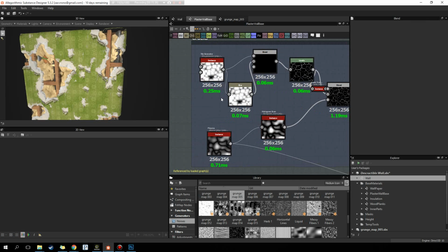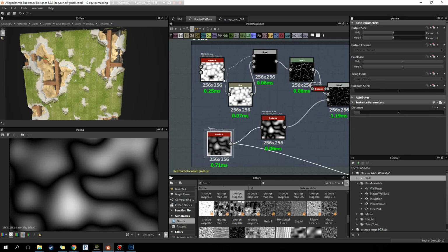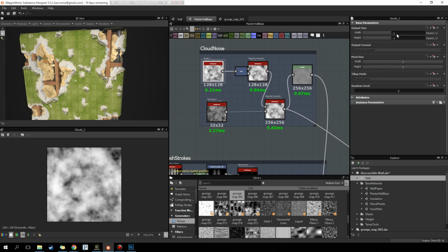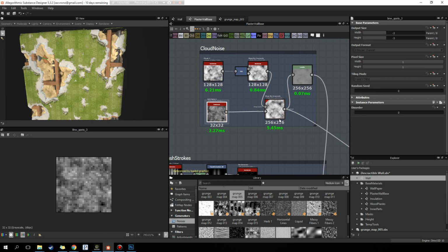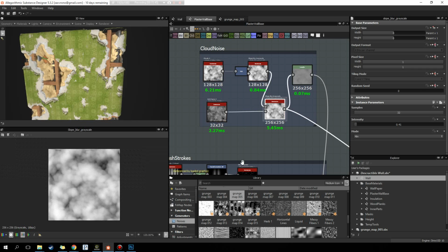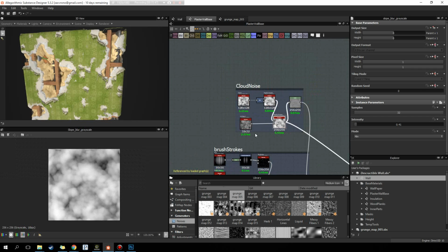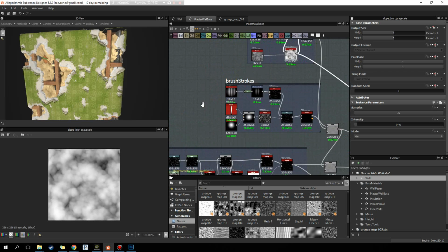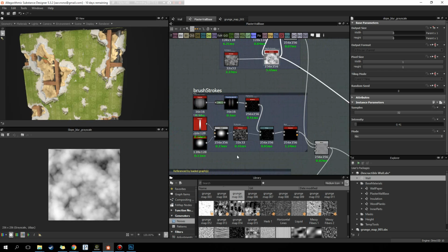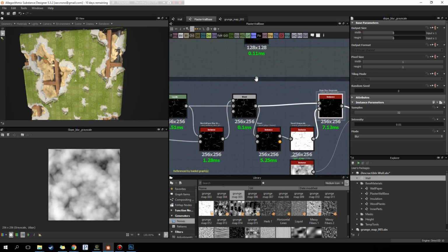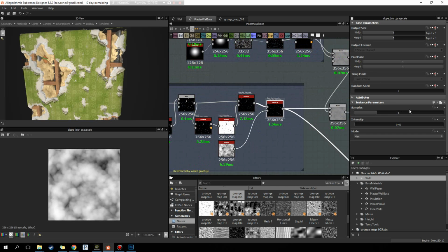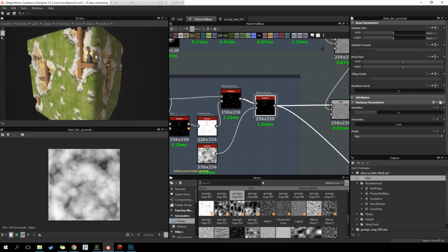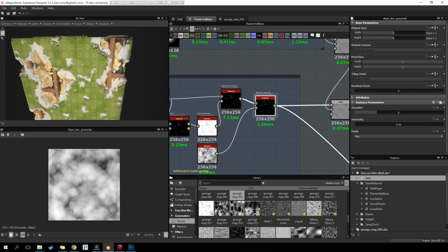So I spend a lot of time doing that, like here. Actually, no, not there. Here. This is a 128. It's half the size of the parent. This is a 32 pixel image. I'm putting it into there and blending them together and upscaling them back up, and just being really careful about that stuff. And then when I have things like even this slope blur, that one's pretty intense, but this one's only 8 samples. You didn't need it as much. So you just have to be careful about that kind of stuff too.